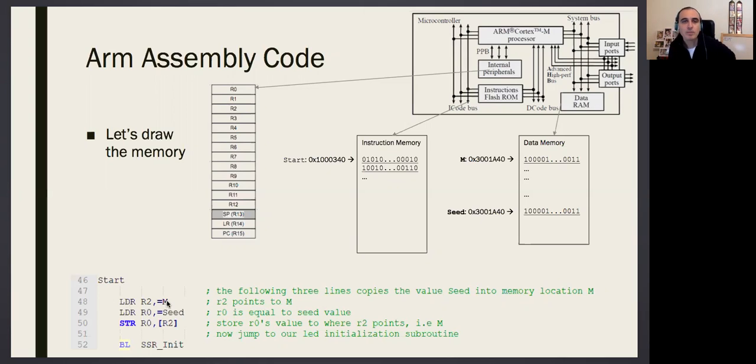And actually, when I write this code and do my operations on this interface, I upload this code to my card. And it writes this code to the instruction memory, starting from an address. Which address, I don't know. For example, it is this address. The addresses have 32 bits, so it is 8 nibbles. 8 nibbles, each nibble 4 bits, 32 bits.